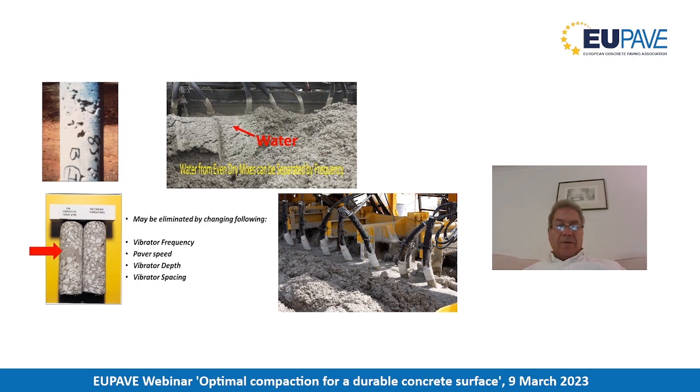And I've got a photograph here in the middle where water is identified, and even with very dry mixes, to get the mix fluid workable, you have to increase the vibration frequency to the point where you will draw water, and it invariably comes to the surface, leaving a film of slurry, and in due course you will end up with surface cracking.